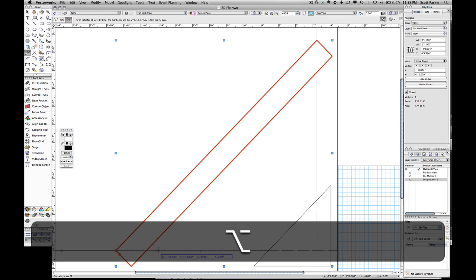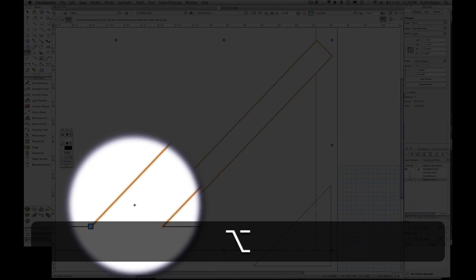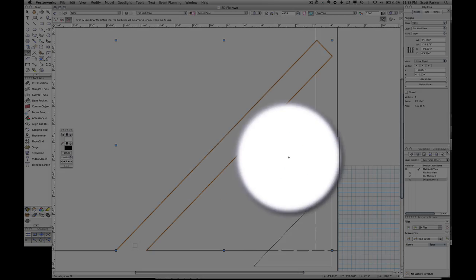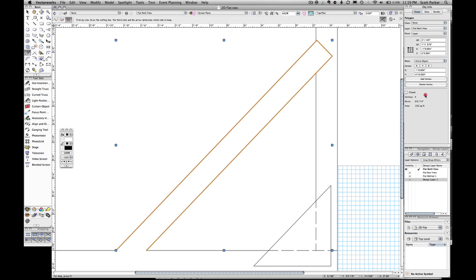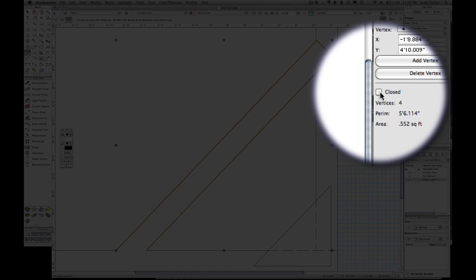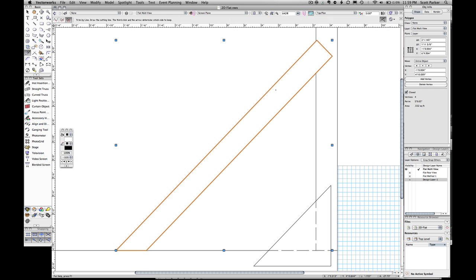This command executes our desired split upon just the selected item. So now I click it and I move my hand up slightly. This little flag says we're going to keep this side of it. And I click again, and as you can see, it slices off the end. And we're going to go over here to the Object Info palette and close our polygon. And there it is, the line is back.